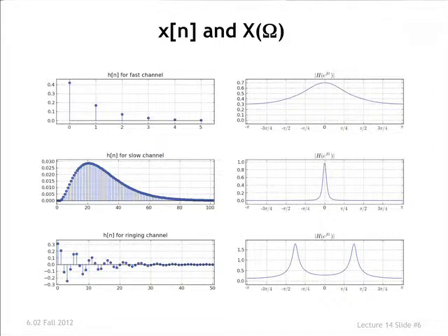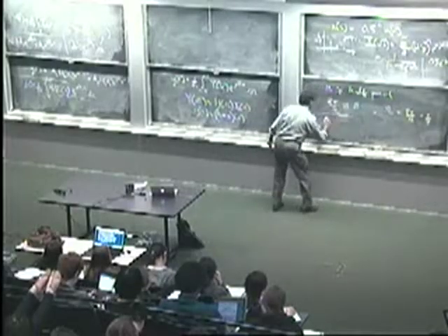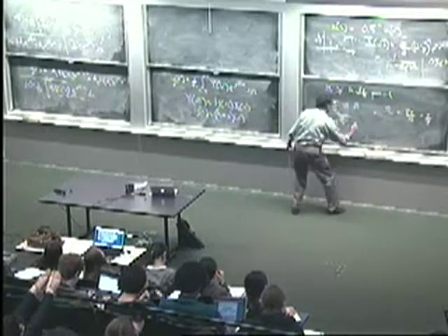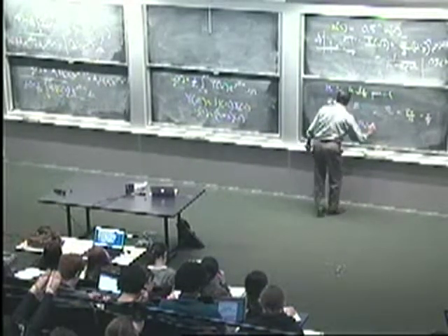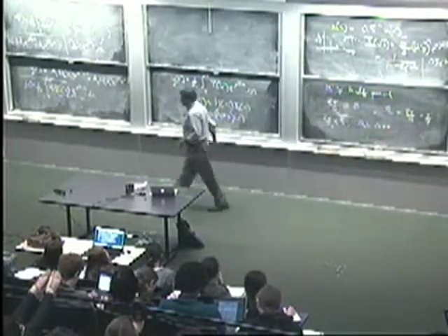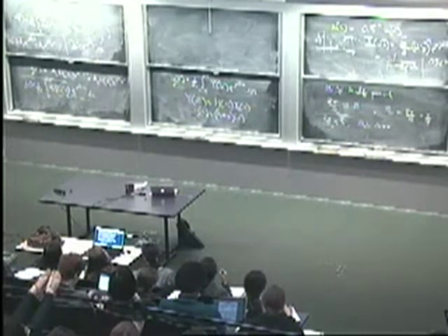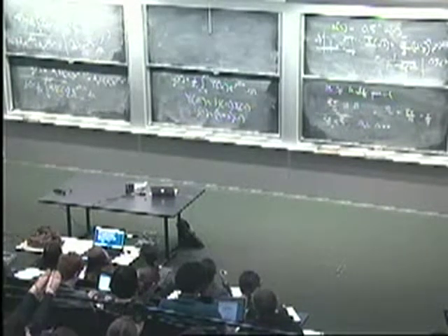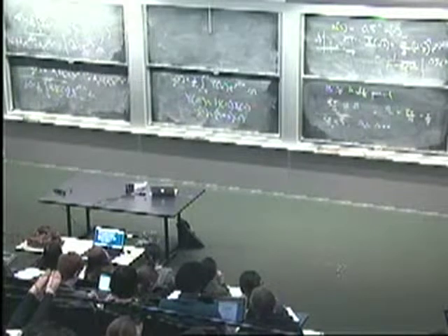And again, you can go through the kind of rough calculation I just made. So we see some oscillation here. Let's estimate the period. That's 1, 2, 3, 4, 5. Let's say it's about a period of 5 for those oscillations. So 2 pi over omega naught is approximately 5. So omega naught is approximately 2 over 5 pi. Right? So we expect to see a spectral peak somewhere around 0.4 pi. Here's 0.25 pi. Here's 0.5 pi. We're about right. Okay, so make these sorts of checks.